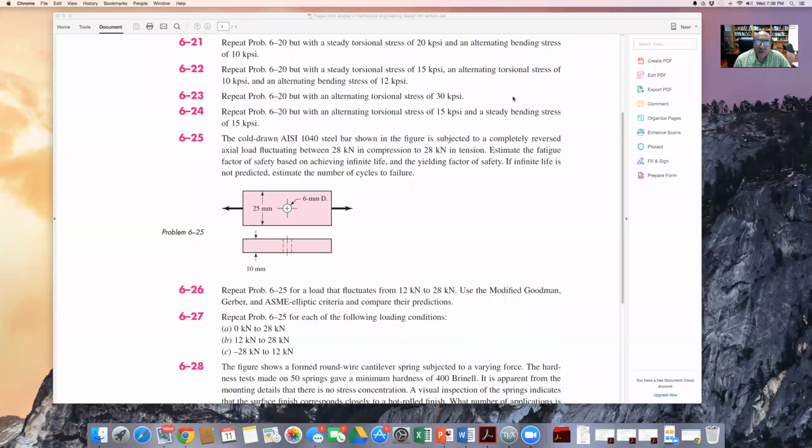What I'll do is review three problems related to fatigue failure, and they show basically how to design a component against failure due to yield by plasticity, or due to fatigue with a limited lifetime or for infinite lifetime. Also, the problems are going to discuss how we can combine different types of stresses using von Mises criteria.